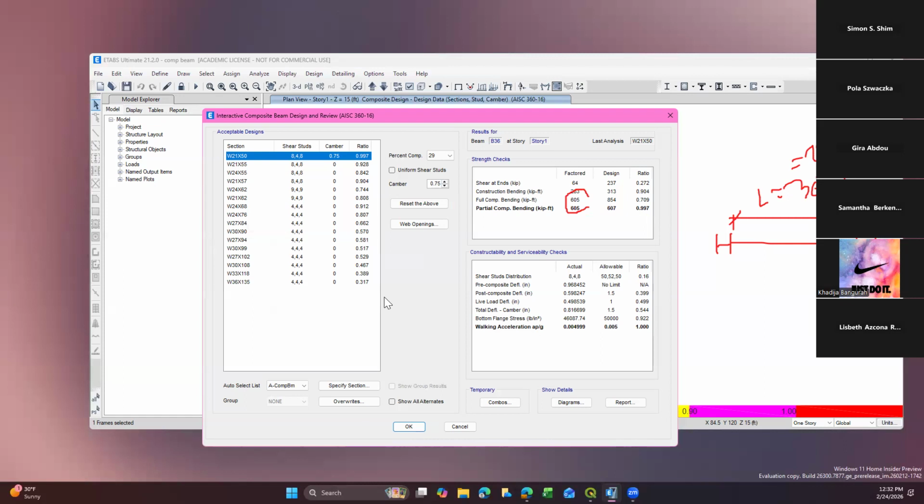So I think in these calculations the bending moment is based on the clear span, not center to center, because the column has dimension. Instead of center to center 30 feet, they're using the face to face dimension. So the girder span length is a little bit less than 30 feet. They use this length and calculate the bending moment here. The capacity calculation is the same as what we discussed. They're also checking deflection: pre-construction, composite, post-composite. So you need to address that the same way.